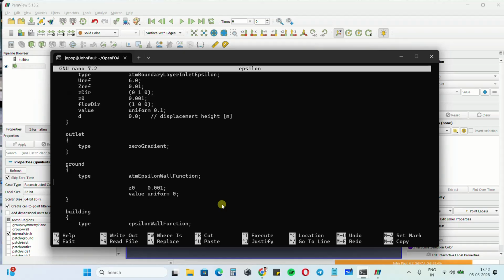And also, in a more realistic way, we talked about the city block lying inside the urban space. So in reality you have different types of patches in the ground. Maybe a region with pavements, maybe a region with asphalt, maybe some region with grass. So at these regions you will have different types of aerodynamic roughness. We are not considering that. We are assuming that the average roughness is uniform. Okay, so that's one assumption that we have, and that's reasonable to have in a moderately dense area.